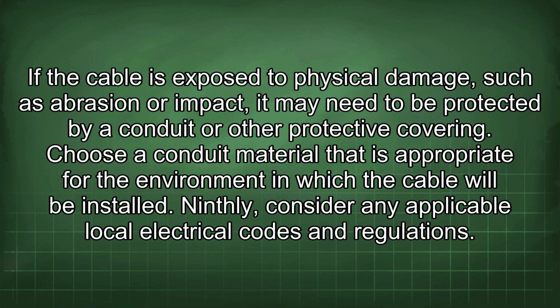Eighthly, consider the physical protection of the cable. If the cable is exposed to physical damage, such as abrasion or impact, it may need to be protected by a conduit or other protective covering. Choose a conduit material that is appropriate for the environment in which the cable will be installed.